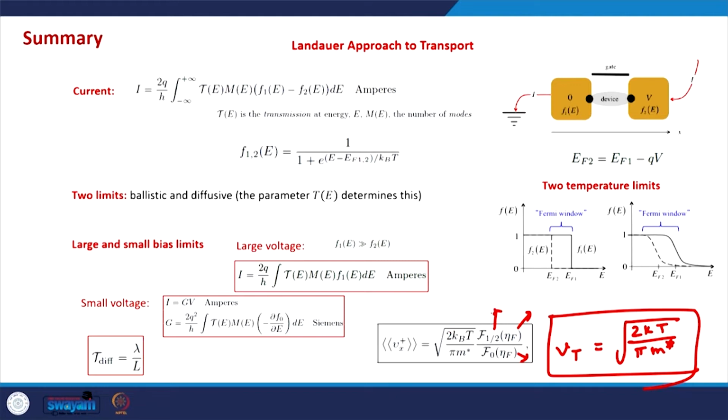In some cases, although, in order to have a better understanding, we try to actually approximate the Fermi-Dirac integrals by the exponentials. So I hope this idea of the unidirectional thermal velocity is clear, and a related idea is the idea of the injection velocity, ballistic injection velocity, that will become apparent in the discussion of the ballistic MOSFET.